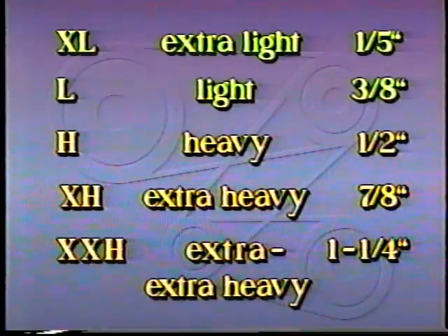5 standard pitches are commonly available. XL, or extra light, with a pitch of 1/5 of an inch. L, or light, with a pitch of 3/8 of an inch. H, or heavy, with a pitch of 1/2 an inch. XH, or extra heavy, with a pitch of 7/8 of an inch. And XXH, or double extra heavy, with a pitch of 1 1/4 inches.